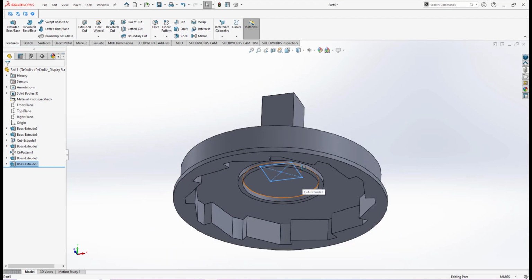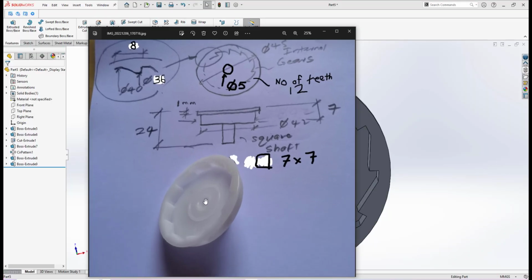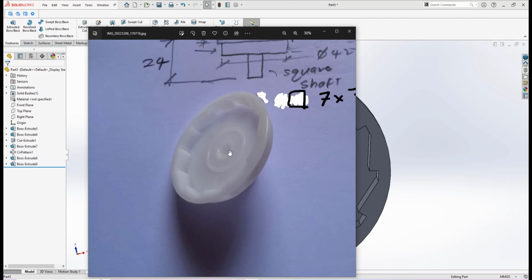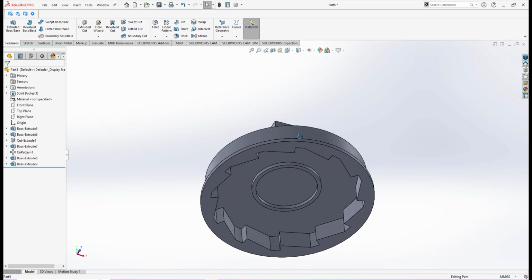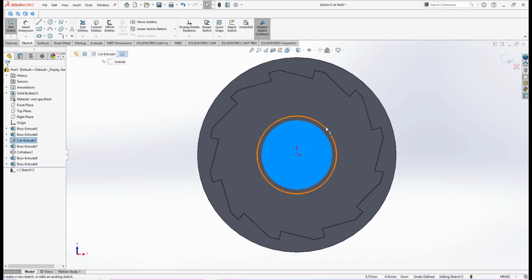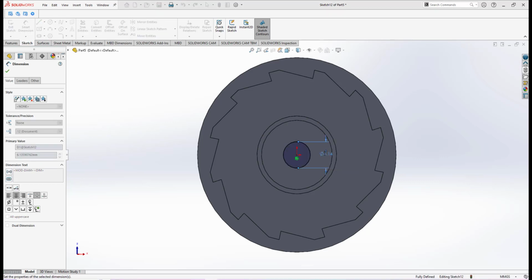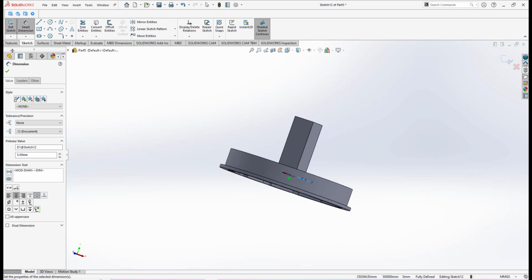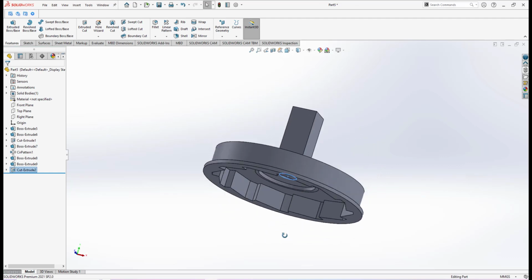Okay, this surface, actually, if you look in the photo, if you zoom in, they have kind of holes. The idea to make a hollow shape, what I think the feature is just meant to save cost of the material. So I would create a hole here. Instead of a solid rod 7 by 7, they have a cut through hole of diameter 5. So I will make an extruded cut about the distance of 15, so we have a hollow rod.